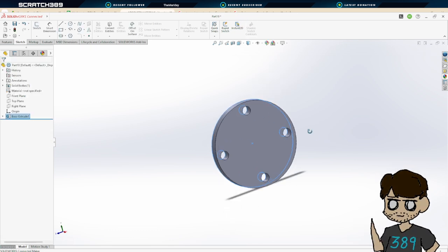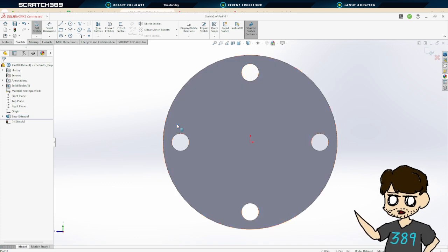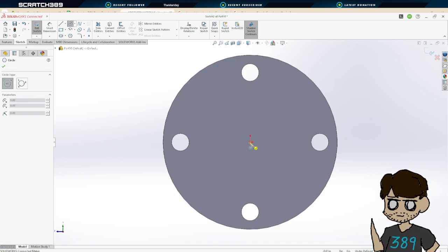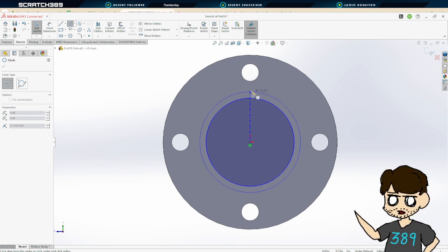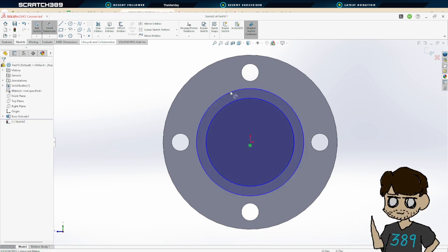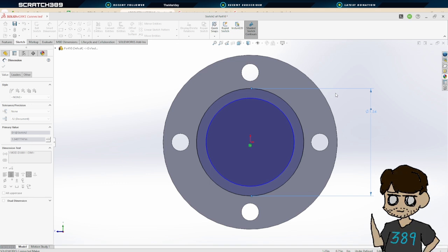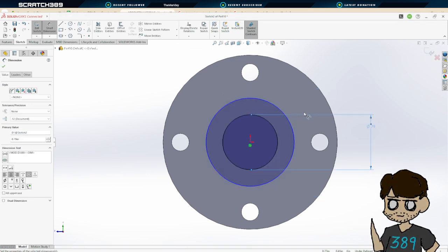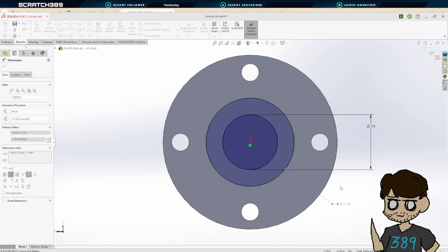And then we simply add another extrusion. And I'm gonna make it hollow as to not waste printer material or time. So let's go 0.79. And this one is 0.5.